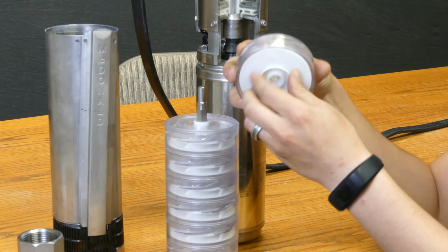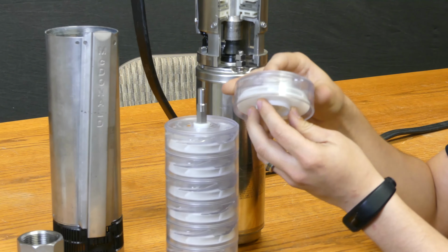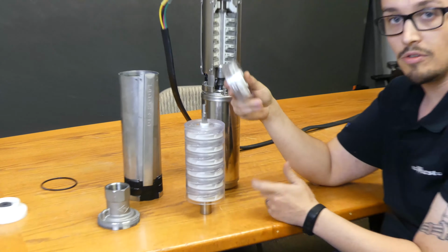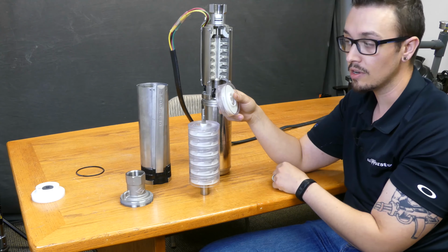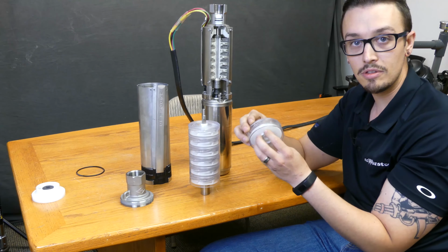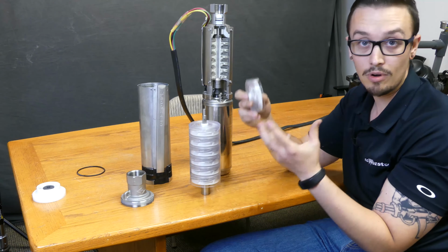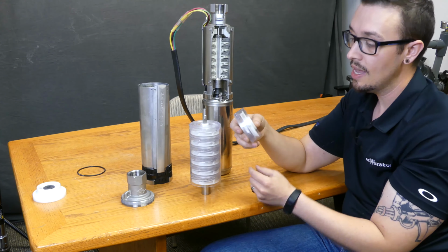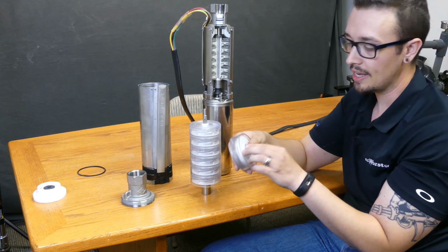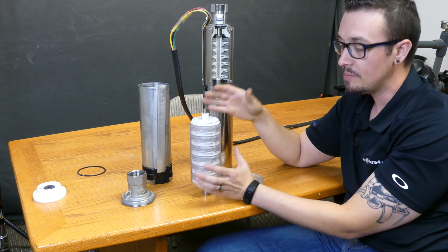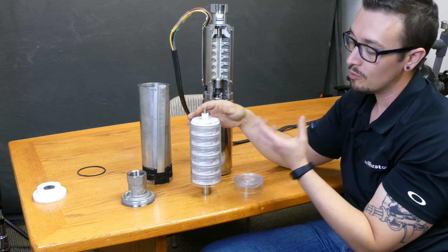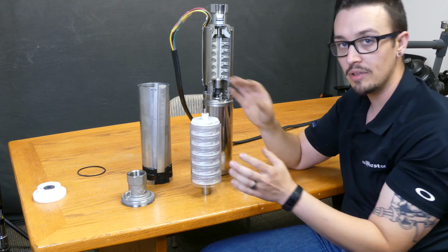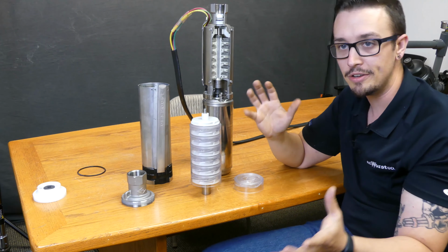Now, it's not a whole lot of friction that you experience, but when these things are spinning at 3,450 RPMs, you can imagine the kind of damage that you could cause. I could probably sit here and do this all day, and that wouldn't equal 3,450 RPMs over the entire day. So when it comes to this style of pump, you're basically sacrificing overall performance and longevity for the ability to operate the entire range of the curve.